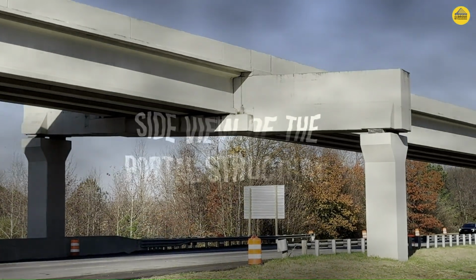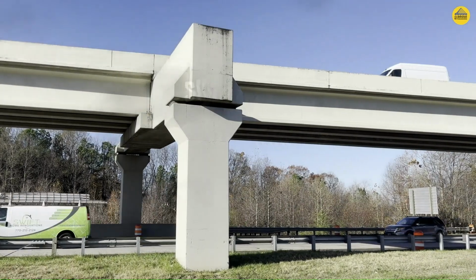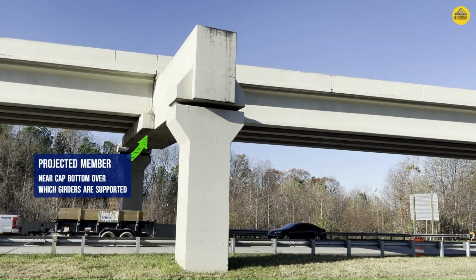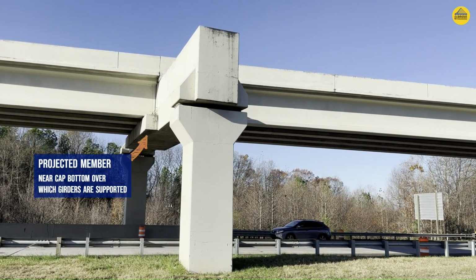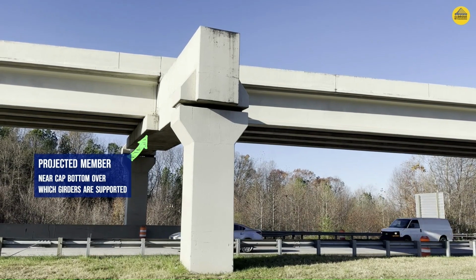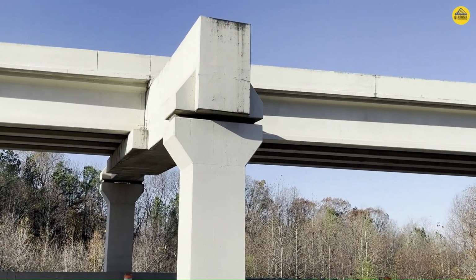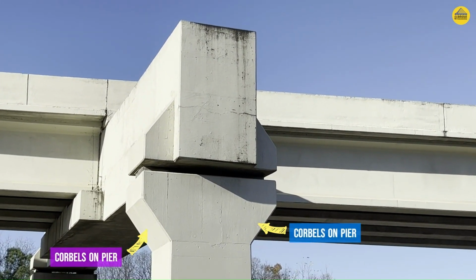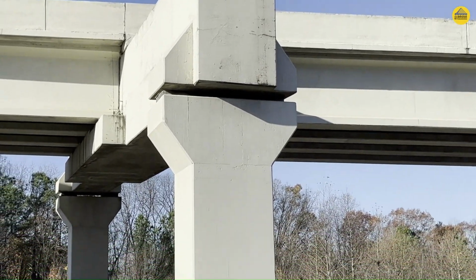It's time to see this portal structure from the side, and in the side view you can clearly see the supporting member over which the girders are placed, and the supporting member is flushed with the bottom of the portal cap. Not only this, a zoomed section also clearly highlights the gap between this portal cap and the portal piers. Please also note that the portal piers have a bracket attachment on either side, similar to the bracket attachment on the portal cap. Between these two bracket attachments, we have elastomeric bearings.